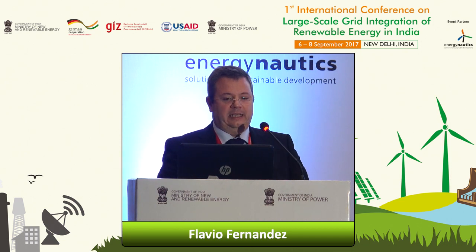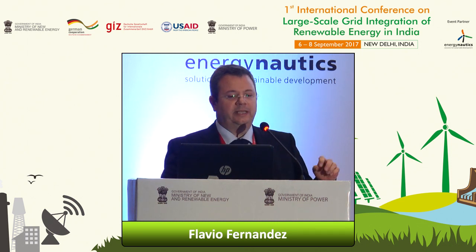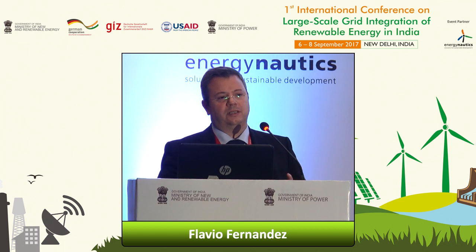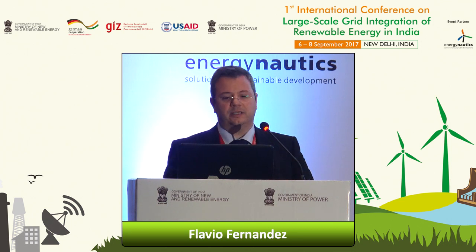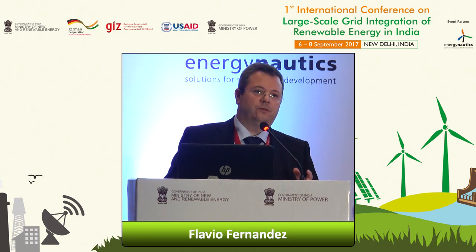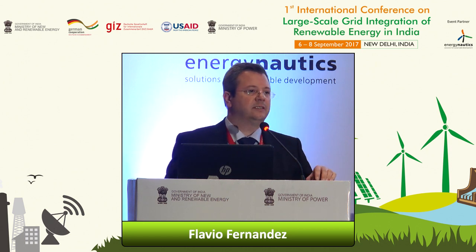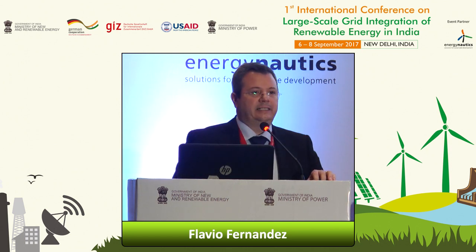Another important issue is numerical stability. Numerical stability means the model can work with the integration step, the simulation time step, typically used for stability analysis in networks. We're talking about half a cycle here, so for a 50 Hertz system that would be 10 milliseconds.